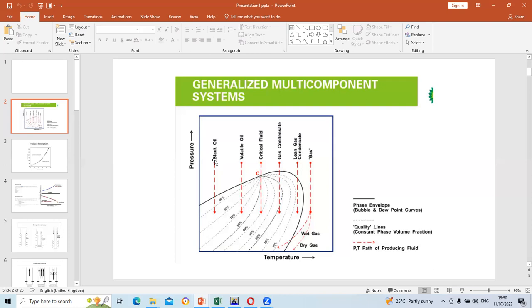So we have our oil and we have our gas. Our gas there, that's what we are going to identify in a black oil model. But as you're moving into the gas zone, where the amount of gas has increased or the gas oil ratio has increased, it is not sufficient for you to characterize each phase as discrete entities. So in that case, they will now be given the composition of the various alkanes that are found inside that reservoir.